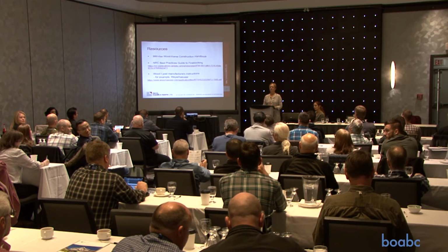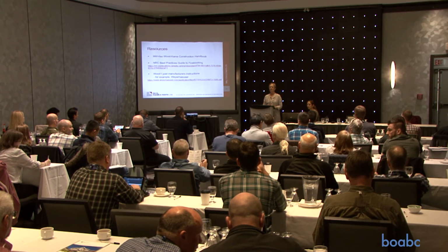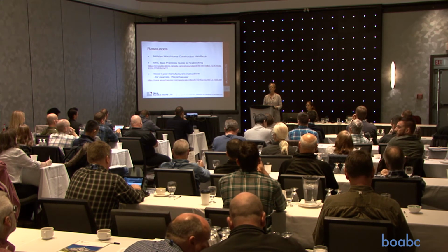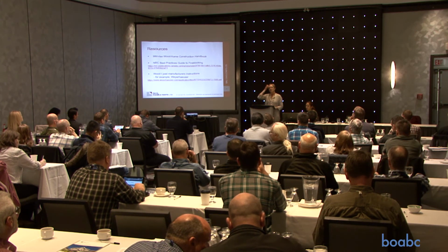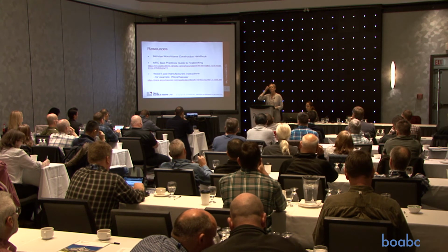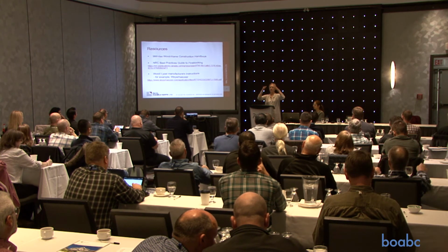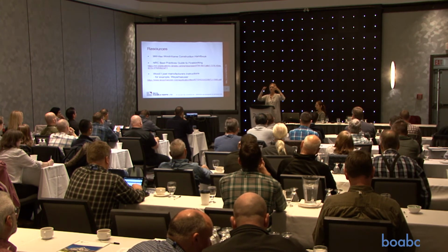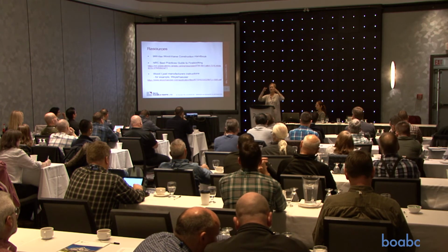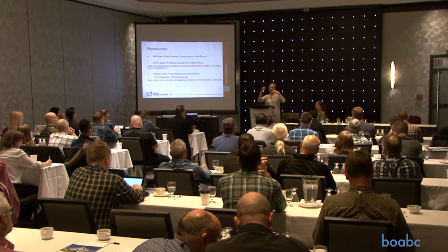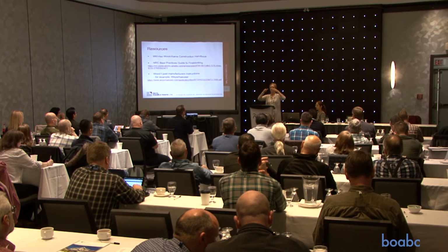Oh, wait. Back to that slide where you had the metal ducting and you lined the space with board. What situation would you need to do that? So if the duct was too big to be an opening in that membrane-only ceiling, because there's limits on size and density and everything, then you basically run the fire separation behind it and it stays inside your suite.